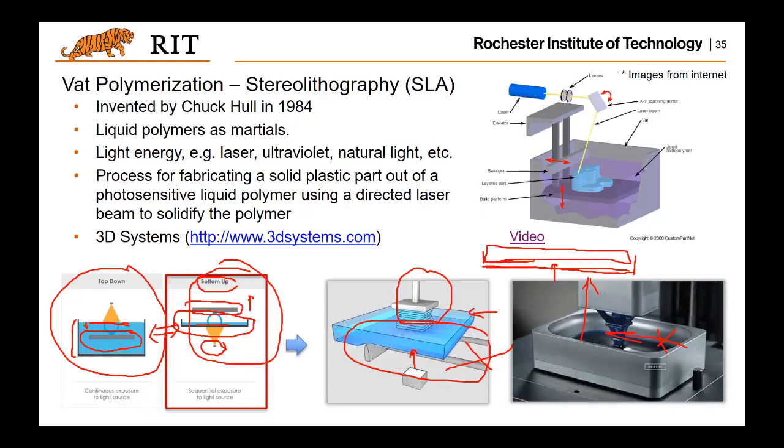That means between the liquid resin and the tank, there's always another actual oxygen layer to make sure they do not touch each other. So in that sense, there's no risk of the bottom of the tank attaching to the newly cured layer of the part. So that's how they eliminate this separation motion, and that's why they could have such a much faster process. But that's not easy.